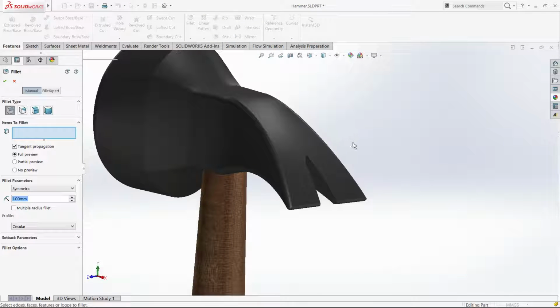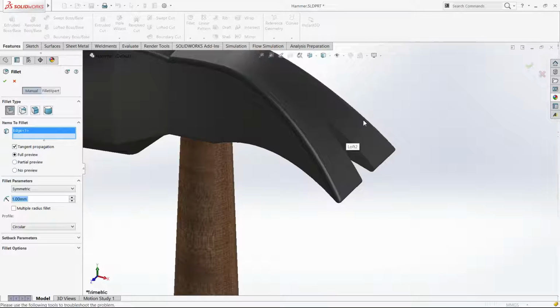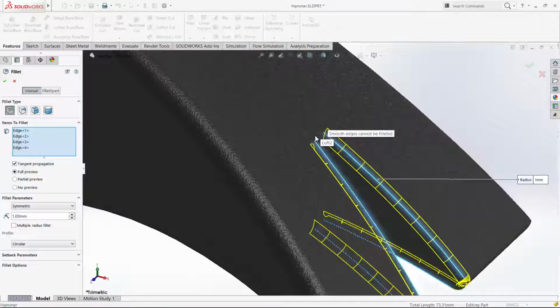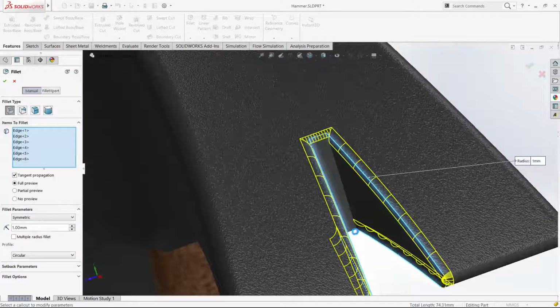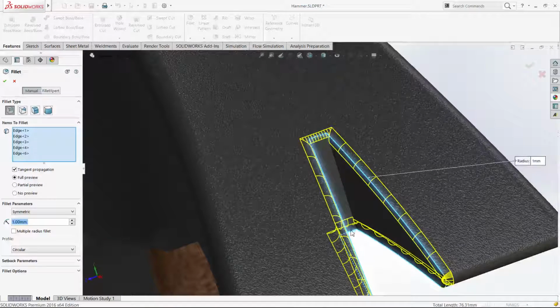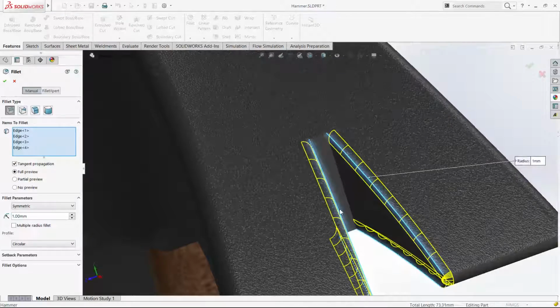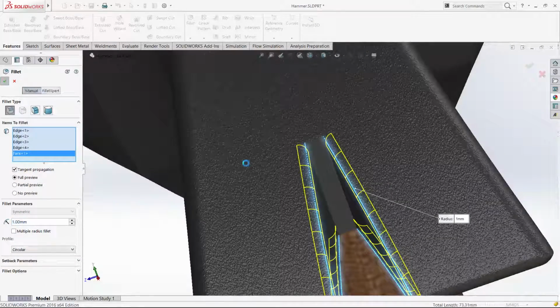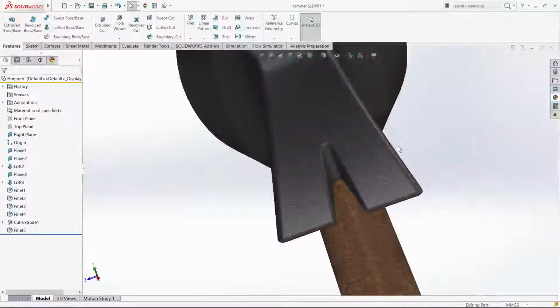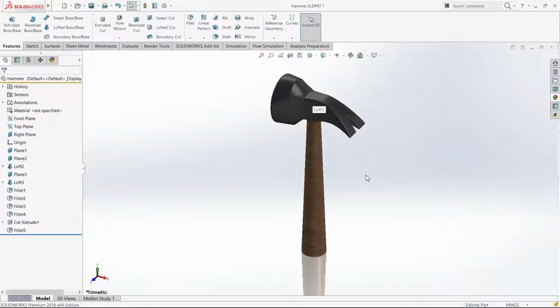And finally, just add the fillets there, and probably there. Oh wait, just like I did last time, I'm going to click on the face, so it selects all the edges of that face, and that's what I wanted. Finish, and I don't have to put the appearance anymore because I did the appearance to the whole part, and there you go.